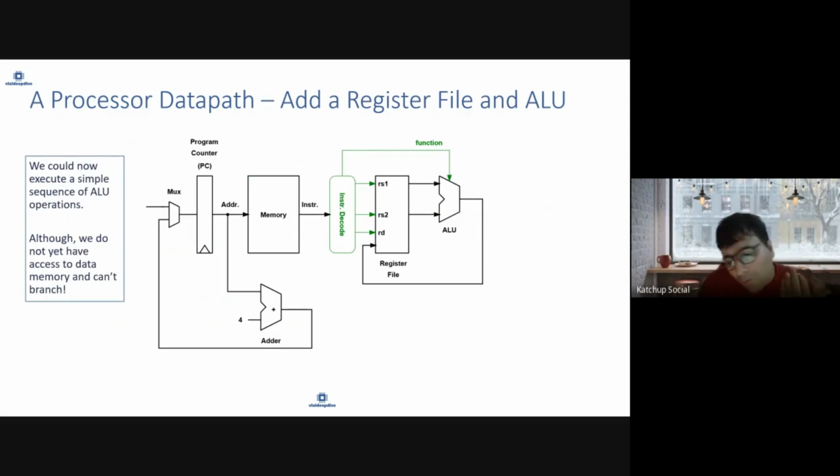Now we want the processor to execute certain operations. So we need to execute this operation. We will add what is known as an arithmetic and logic unit. We're not going into details of the inside of the ALU, but basically you can do add operations, XOR operations, and other addition, subtraction, multiplication, whatever operations you want to do. So it's a simple arithmetic logic unit. It can be coded in simple Verilog like a case statement based upon X, and this is covered in our basic Verilog code.